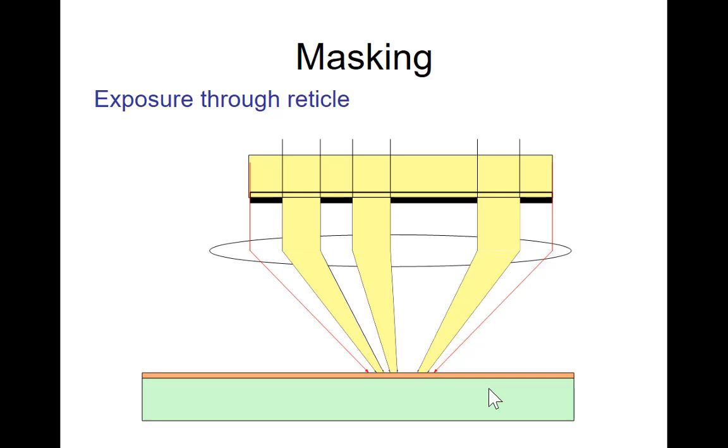And why do we mask the wafer? We are making different areas, for example a gate area and a source area. If I want to make a gate, I need to selectively put some material in one area. So I use something to cover most other places and just leave this part open.